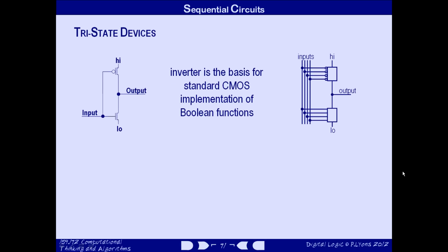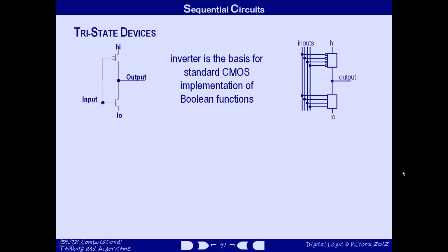So this circuit is always driving its output wire to a particular voltage, high or low. And if we connect several devices based on this design to a single output wire, then we'll get the sort of electrical conflicts that we discussed before. What to do? Well, we need a circuit that can sometimes disconnect its output wire from both high and low voltages so that something else can control it. Take the inverter circuit, and remember that the other devices have the same general architecture, so this approach will work for more complicated gates as well.